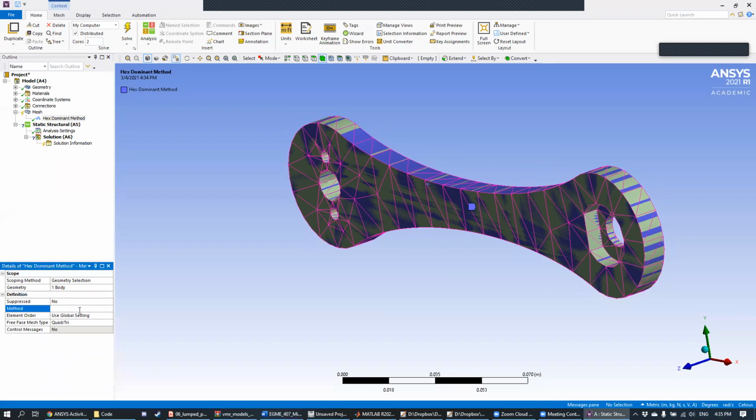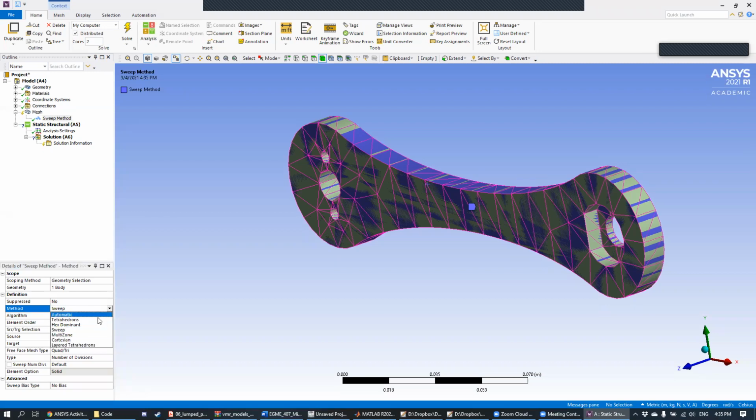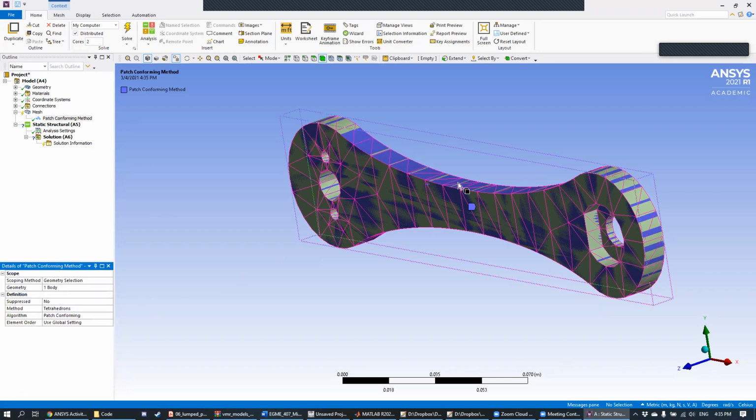For tetrahedrons, they're great for objects that have a lot of curves to them. Tetrahedrons have this really nice property in that they can fill any 3D space exactly. So if you have a very complicated, very twisty geometry, tetrahedrons are your way to go. So that one basically fills in the gaps. Exactly. For this kind of object, where you can see it's kind of curvy, my guess would be tetrahedrons would be a little bit more efficient here.